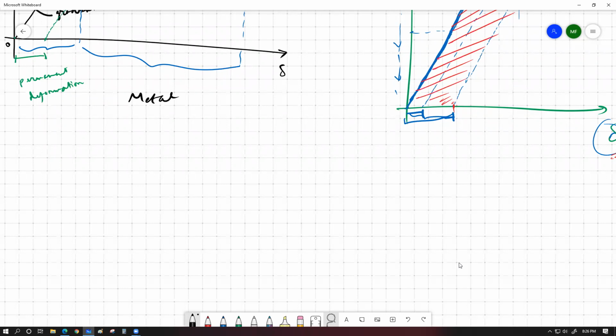Ductility means that it has a large plastic deformation region before breaking under tensile stress. Tensile stress means that you are pulling the object from two ends, or maybe from multiple ends, and before the object starts to tear apart, it is going to show a significantly large amount of plastic deformation. Before the object breaks, it starts to become wires. So a simple thing to remember is that ductility means the capability to become wires, whereas malleability,